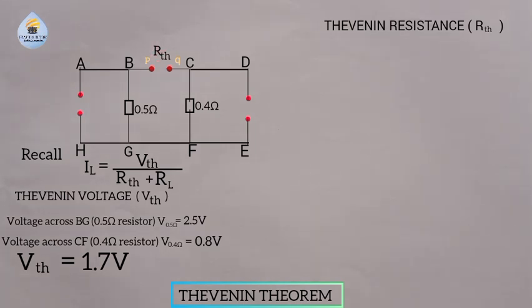In doing that, as we have removed the 2 ohm and the 5 ohm, current cannot flow along that path anymore. So I can likewise remove CDEF this way and remove ABGH this way, right? So I'm left with this.